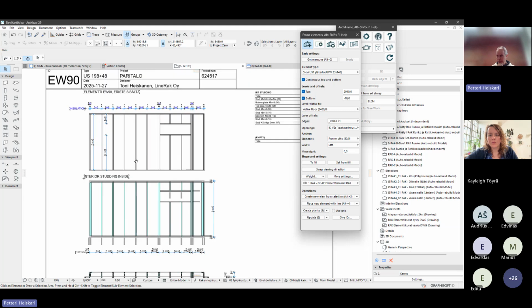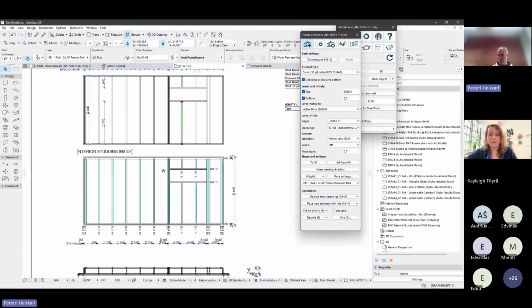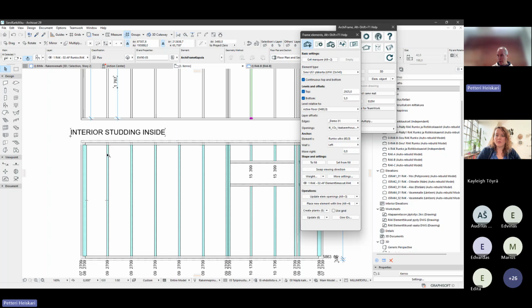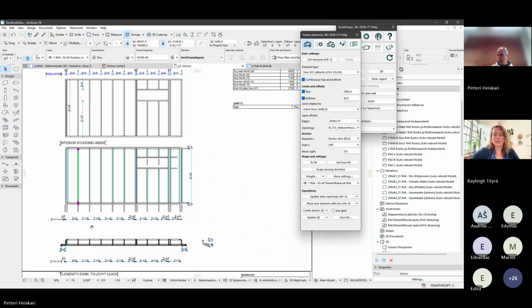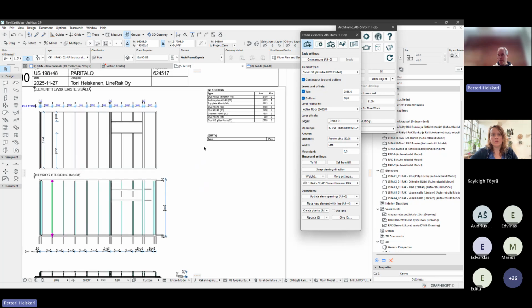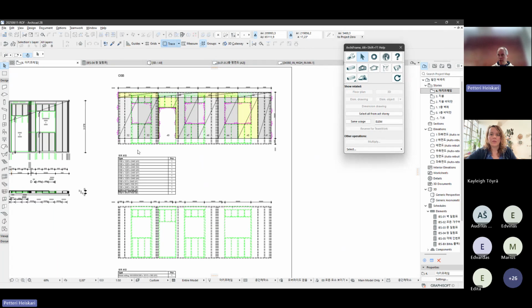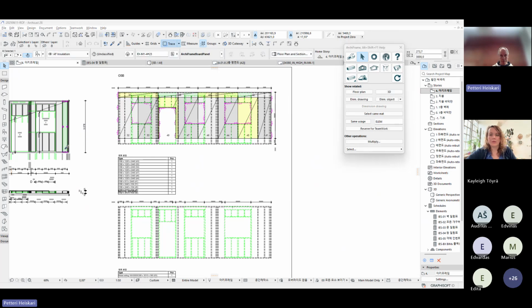Then we have projections from inside this for insulation cutting, basically the width of the space between the studs. Then we have the studding, additional studding here from inside, and the related cut list for the internal studding. Here, if we modeled insulation, it would be here. And for example, in this space factory model here, the insulation is modeled and it's visible here also in the element drawings.